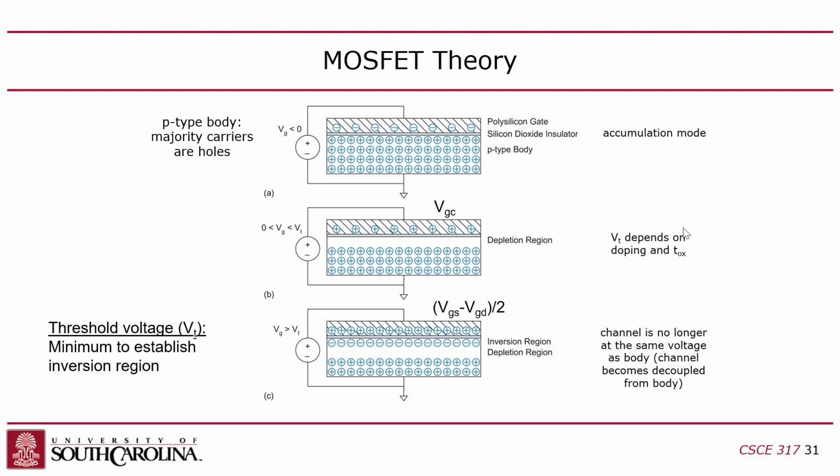you have the gate, the oxide, and the channel become a thing, but then this depletion region is going to decouple the substrate from this channel, right? So the problem here is that when you measure the voltage difference between the gate and the channel, the bottom voltage of this capacitor, you just cannot assume it's ground anymore.